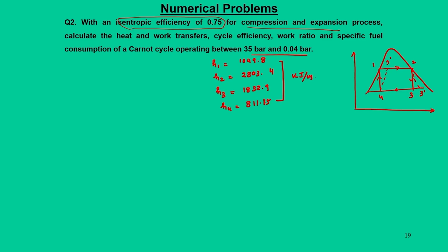Now we put in component efficiency for the compressor and turbine. So, we recalculate turbine work. W23 dash is equal to the efficiency of the turbine into H2 minus H3. By putting in this number, we get 728 kilojoule per kg.